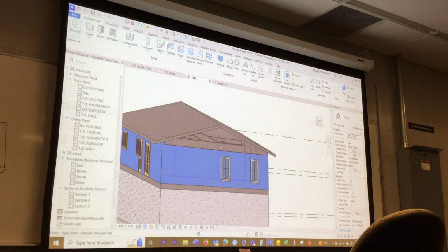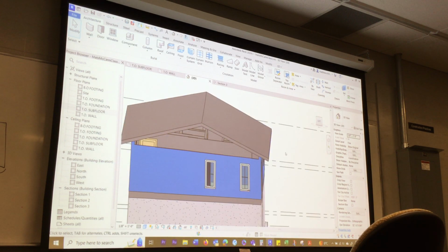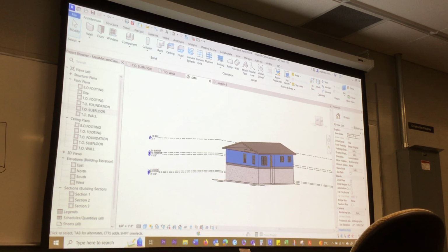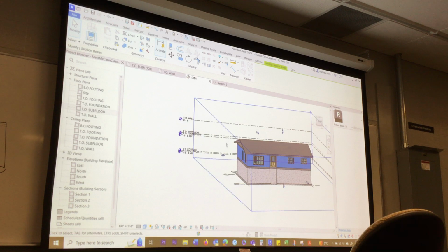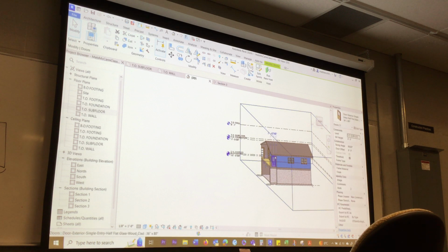Now, I'm gonna go inside the house, I'm gonna peek, and I go, ooh, nice. The other thing I can do, because I'm a space ranger, as they say, I'm gonna turn my section box on. I'm gonna light it up, and I'm gonna slice the house right about there. You guys remember section box? I did that kinda quick.